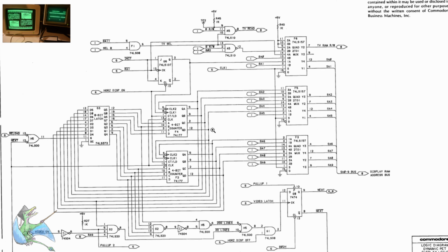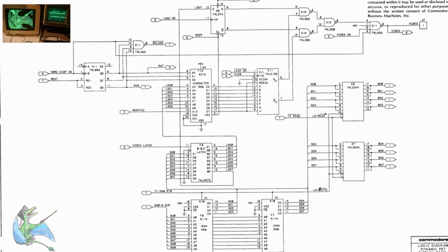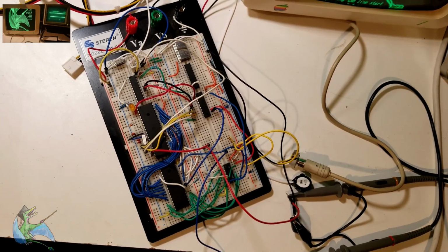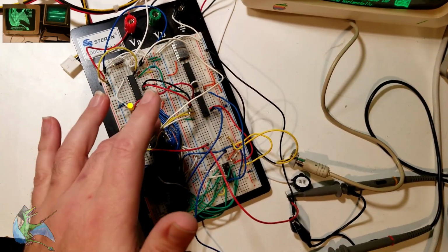Like I mentioned in the first video, 64-column video was very common on these ancient computers. In part, it was because if you make your video a power of 2 wide, then you don't actually need this latch anymore, because 64 is easy. You can just let a 6-bit counter run over and over again. So that's how a real machine does it. And that's exactly what we're doing on our hardware, essentially.